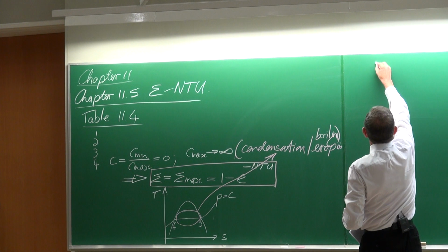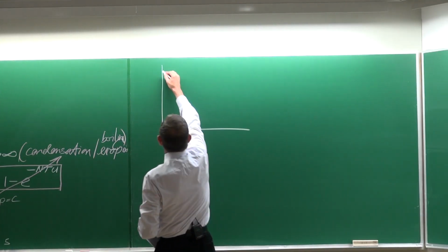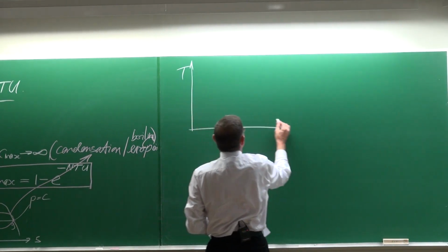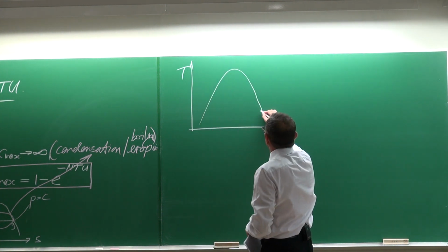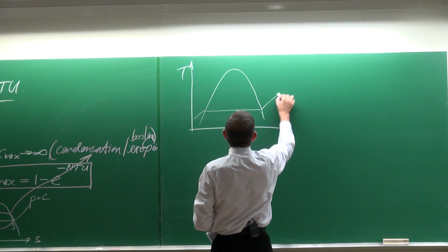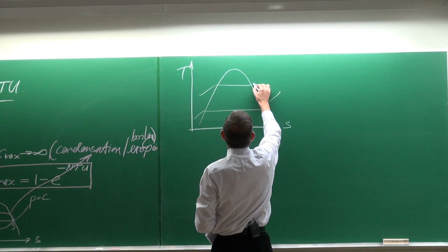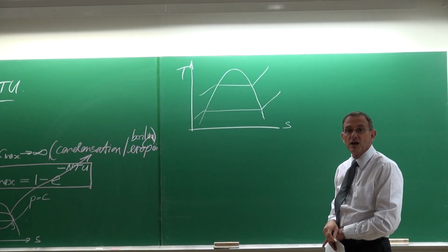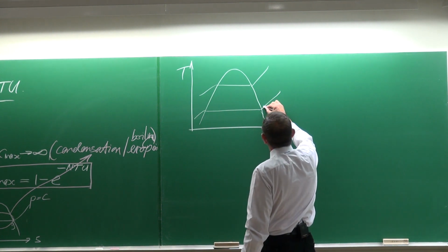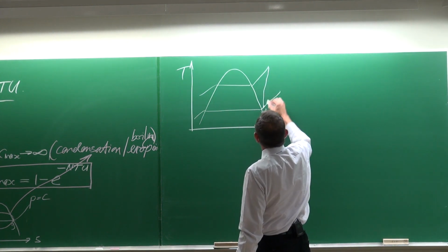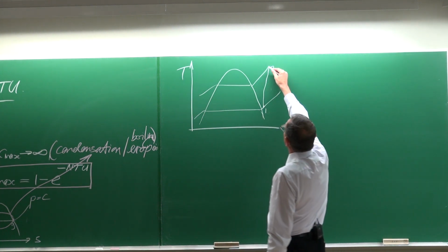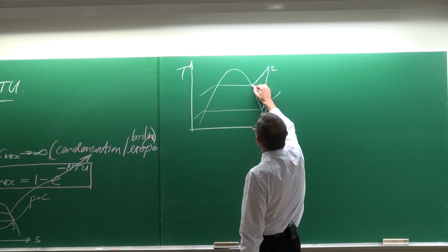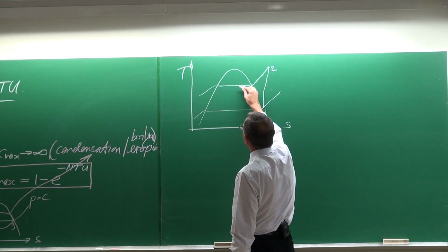And that happens a lot, typically in air conditioning and refrigeration systems, as well as in a Rankine cycle. We've got the 2 pressure lines, like that. In a vapor compression system, we will have a compressor that would compress the fluid from 1 to 2. Then there will be a little bit of superheat and it will condense.